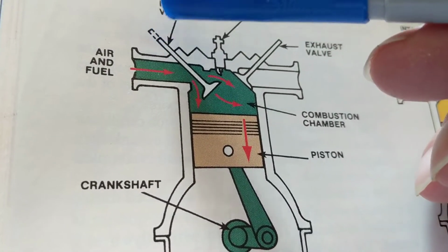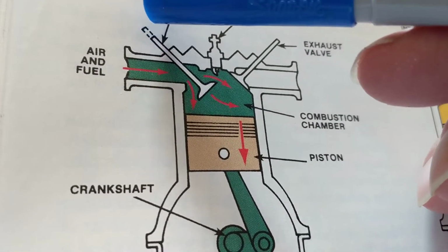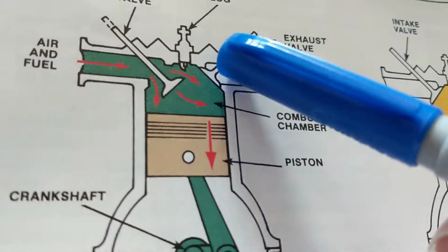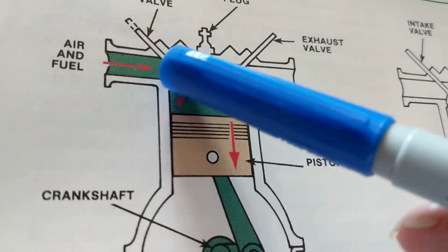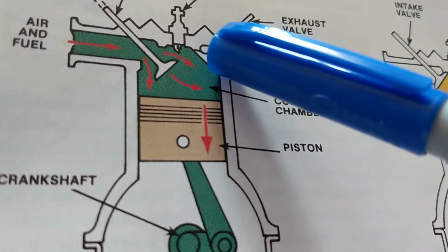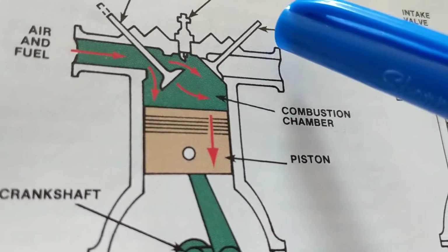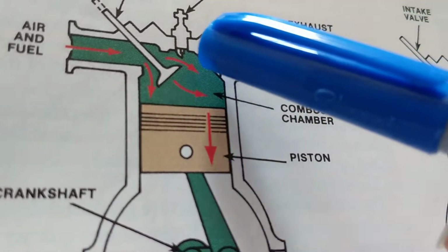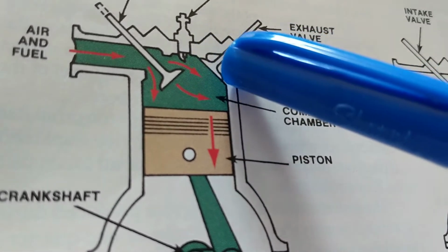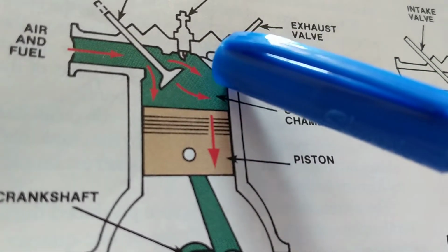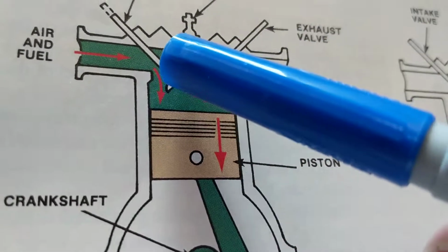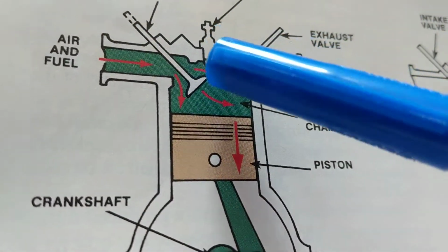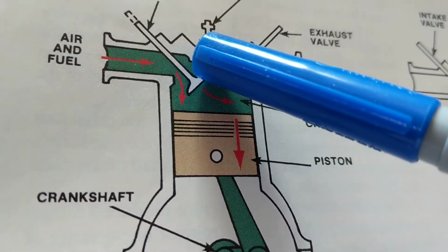You see this dotted line over here? That represents the position when this is closed and when this is open. As you see, look at the one that's closed, look at the one that's open. You see this valve is seated right here, seated over here, closed position. It doesn't let anything in from here to here. As soon as this opens by the camshaft pushing it down, see the area over here, the space is open.